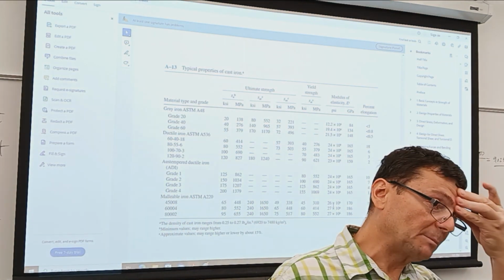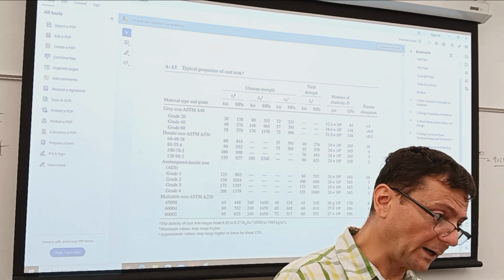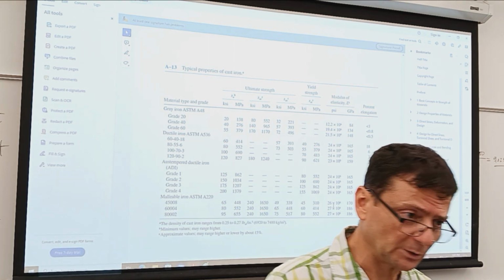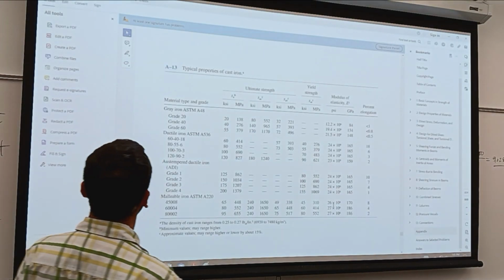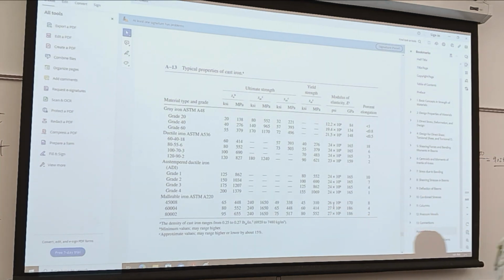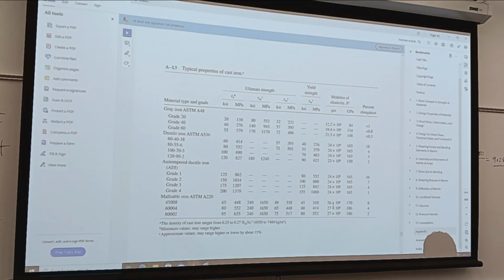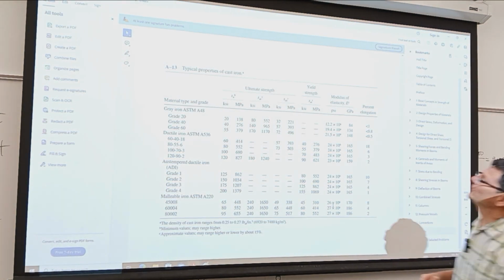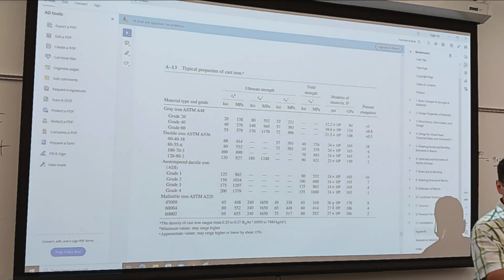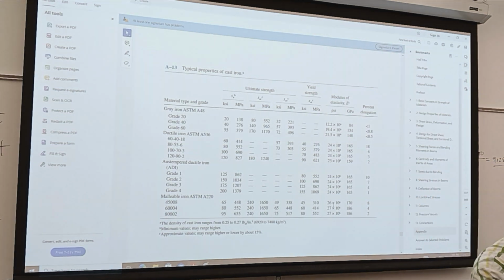it has high carbon content, going towards 2% carbon content. And there's too much carbon, and as you cool it, it precipitates as graphite flakes. Although it can be trapped in the crystal structure, graphite flakes can be controlled with additions like silicon.